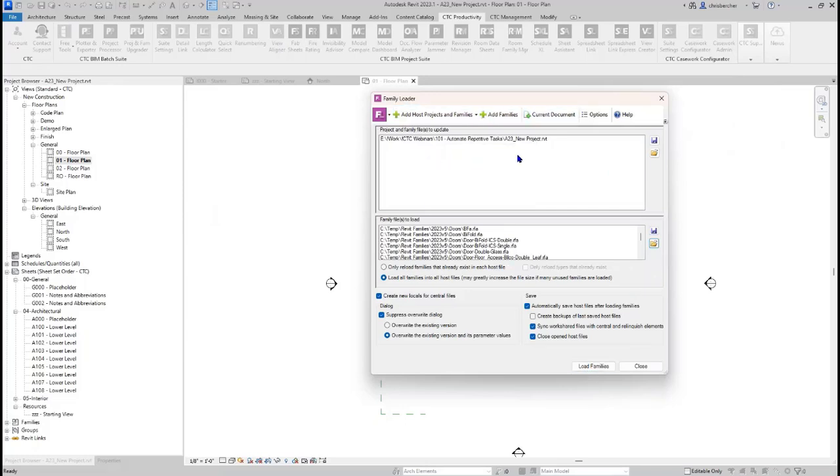And you can do the same thing with your projects list. So maybe you are making changes, or maybe you've got a handful of templates that you're managing, either for different Revit versions or for different project types or different clients that you work for, like whatever the case may be. You can specify a list of those projects here, and it's a savable text file again, just like the families were.